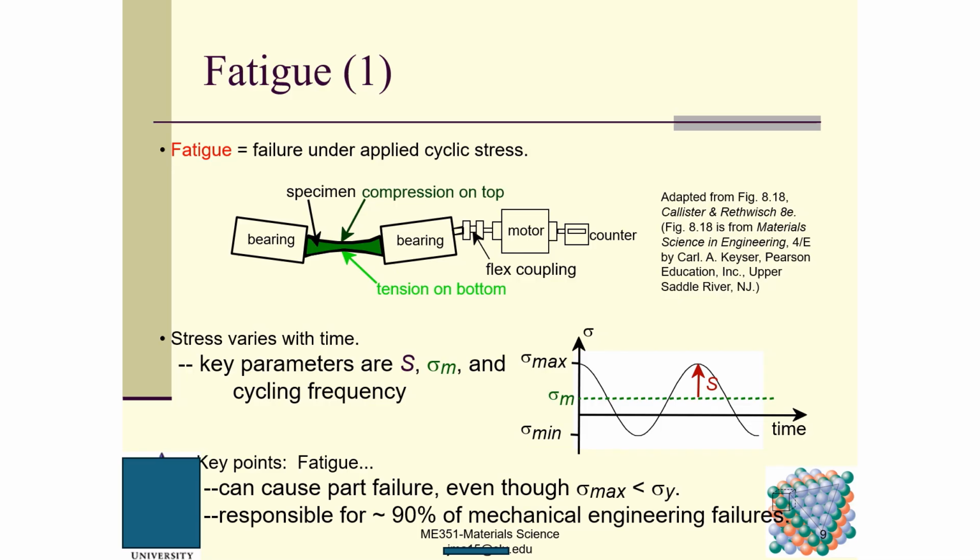Whenever you want to design components or a system, you need to take care of the loading conditions, especially if a component or machine is operating periodically and will experience periodic or repeated loading. If this is the case, you need to conduct fatigue analysis. Otherwise, it's kind of dangerous.